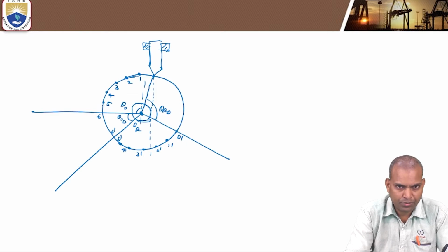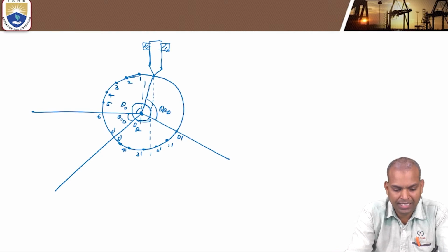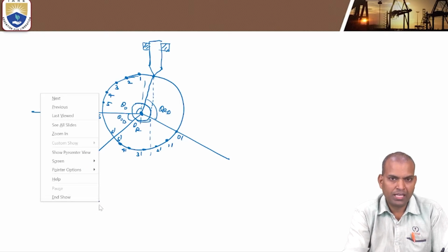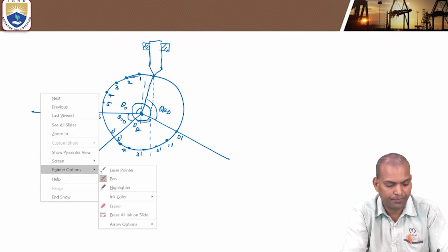the angular displacement points. Now, here we have to draw tangential lines because the contact axis of the follower is tangential to the offset circle. So all these lines should pass tangential to the offset circle, passing through these divisions. Those are the reference lines in order to mark the displacement position of the follower for a particular angle of rotation of the cam.